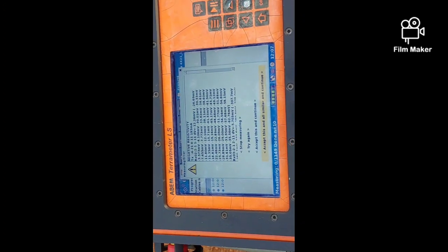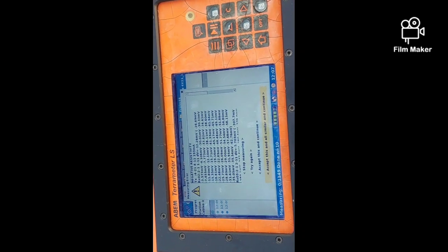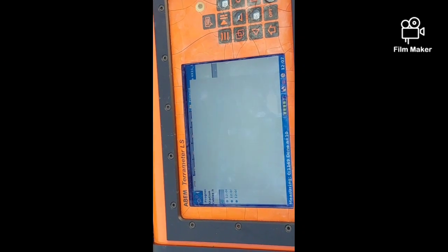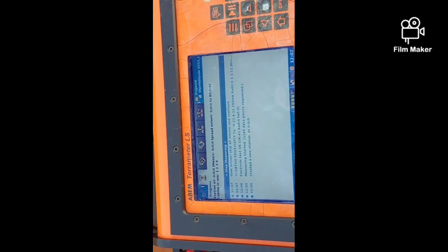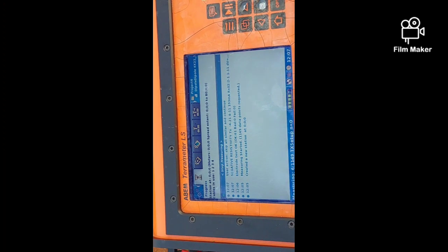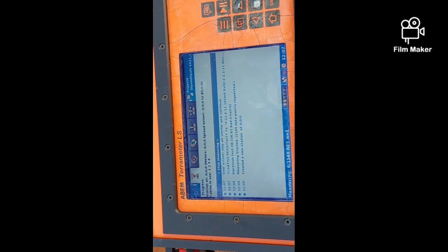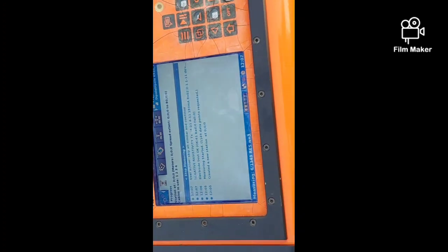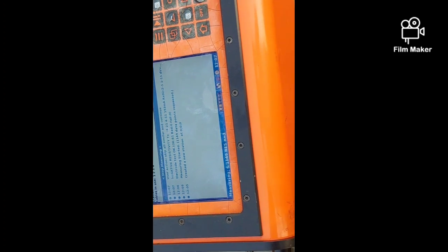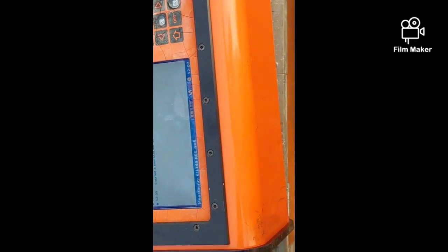We will continue with negative apparent resistivity, because a few points will come where these electrodes are not aligned in a straight line. At that point, you will get negative apparent resistivity. Because if you see the formula, rho is equal to k into delta V upon I. Delta V value will not be negative, and current will not be negative, and k depends upon the spacing and the distance.